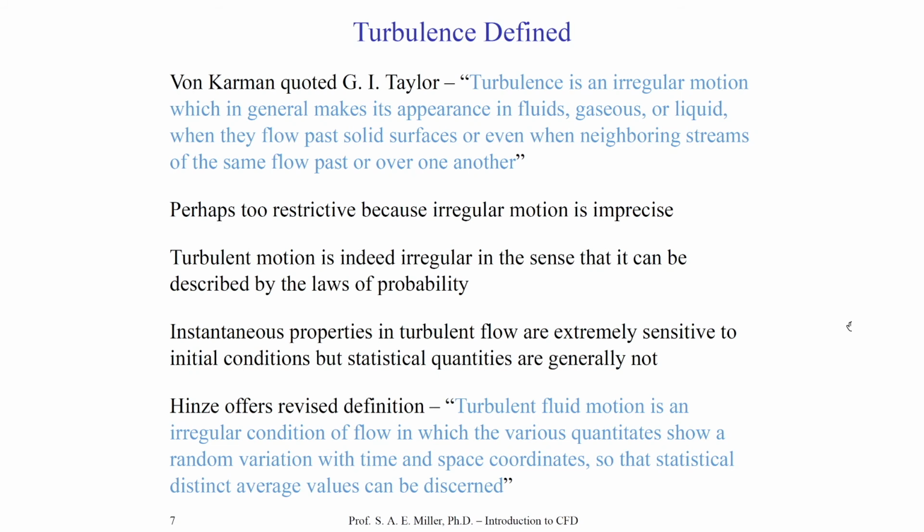Of course, statistical quantities are generally predictable in turbulence, in that they will be agnostic to these large changes in the dynamics of the temporally varying flow. For these reasons, it's probably unlikely we will ever be able to compare a DNS, direct numerical simulation, of a very high Reynolds number turbulent flow with any type of carefully controlled experiment, because the initial conditions and boundary conditions are too sensitive. We will not be able to compare the exact pressure time history, for example, in a turbulent flow.